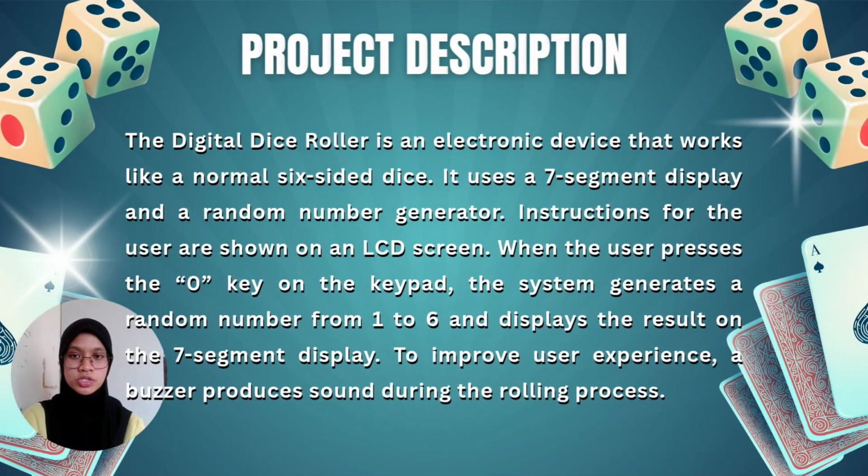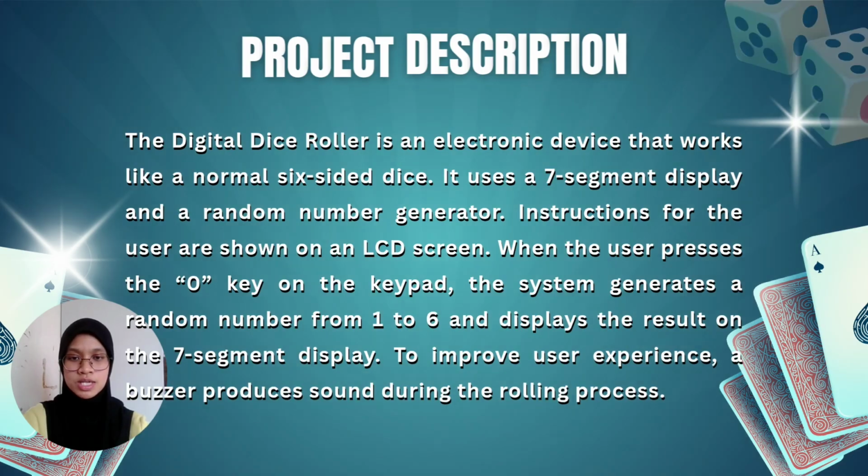For the project description, the digital dice roller is an electronic device that works like a normal six-sided dice. It uses a 7-segment display and a random number generator. Instructions for the user are shown on the LCD screen. When the user presses 0 on the keypad, the system will generate a random number from 1 until 6 and display the result on the 7-segment display. To improve user experience, the buzzer will produce sound during the rolling process.